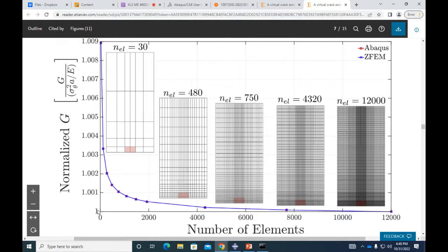Here, 1 means that we don't have any error with respect to the analytical solution. So it's basically a relative error of 0. Where should I have stopped if I was doing this on my regular daily basis? Around this element size, or maybe here at 2000.